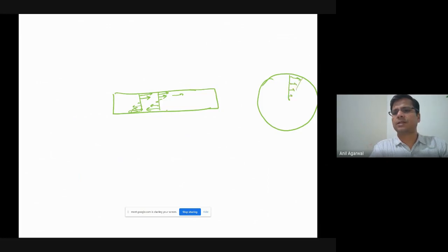Which plane is applying that shear stress on this plane? The plane that is outside of the plane of my screen, right? So there are two planes that are matching each other. If you can see here, watch my hands. One plane, the other plane, and the other plane wants to move with respect to this plane. So the points that are farther away from the centroid are moving more with respect to each other, and therefore they have higher stress. Similar thing happens here. So these are the shear stresses that would be developed.